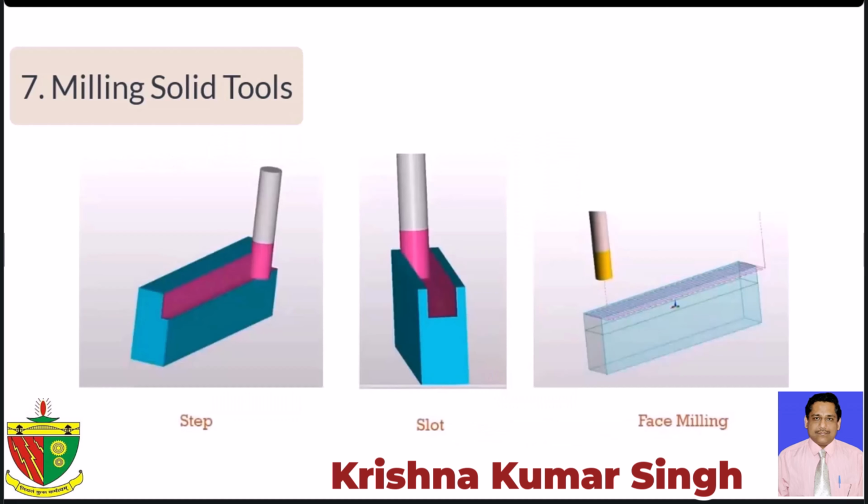To conclude, square end mills are mainly used to make steps, slots, or flatten small areas. Generally, they are used in areas where there is a large depth of cut compared to the area size.